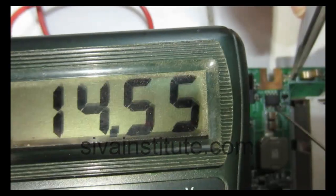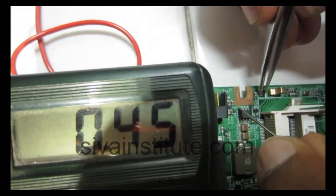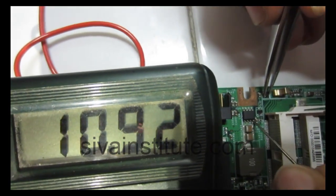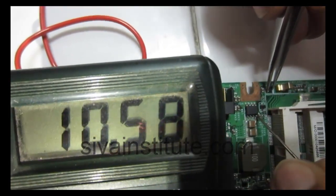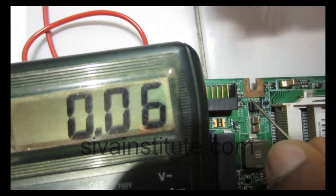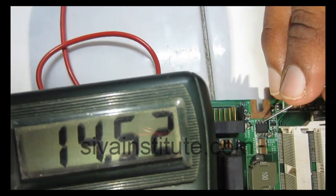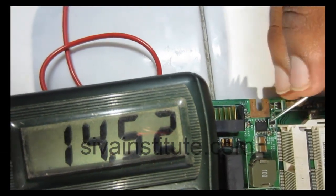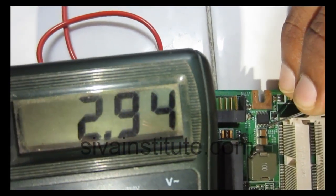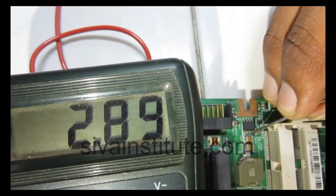The gate voltage goes high and the output goes to 0. When the gate voltage goes high, the output voltage goes to 0. With no short, the output voltage is 14 volts. Gate voltage at pin number 4 is 3 to 4.5 volts. Okay.